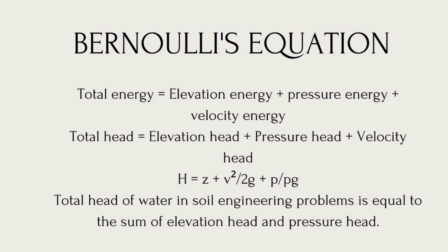As you see in the mathematical equation here, total energy is equal to elevation energy plus pressure energy plus velocity energy. Total head of water in soil engineering problems is equal to the sum of elevation head and pressure head.